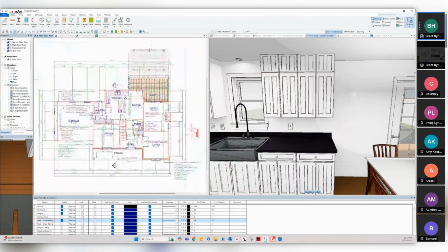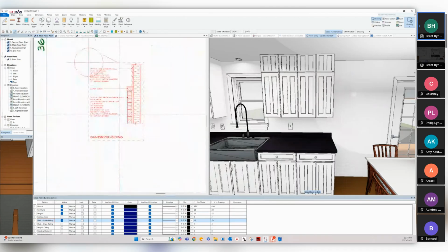The power of a nested drawing, for those of you who didn't foray into nested drawings, is that they're drawn in one spot, but they can be utilized in multiple locations. So let's say you're doing an apartment building, you can draw the one apartment and then add the nested drawing across the hall and down the hall, so that when you change one, they're all changed.